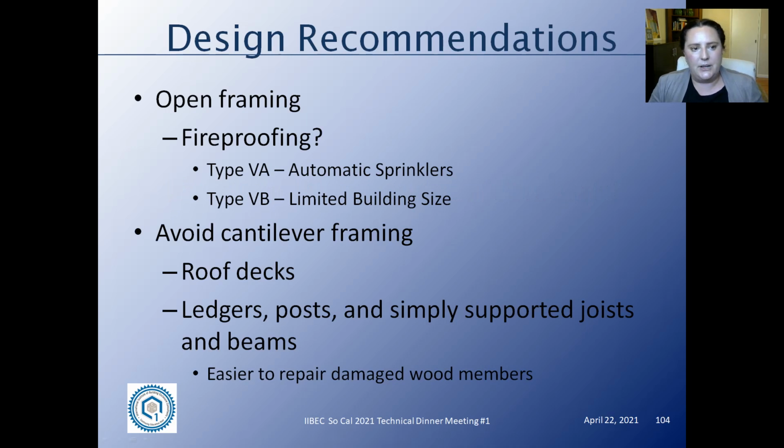So one design recommendation is to consider not doing an enclosed soffit anymore, and to just use open framing. If you do an enclosed soffit, you have to expect that you're going to need to do destructive testing on that enclosed soffit on a regular 6 to 9 year basis in order to do these inspections. The issue with that is there are some fireproofing requirements. Exterior walking surfaces need to be fire protected. One way to do that is automatic sprinklers, or to limit your building to the Type 5B building type.